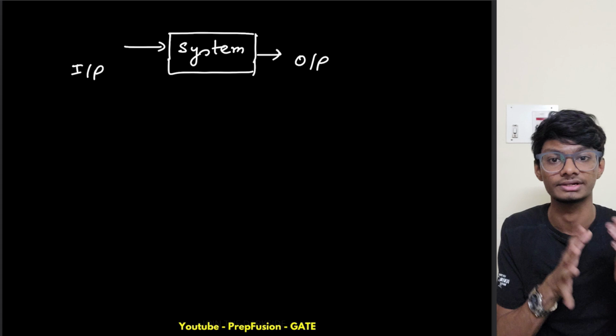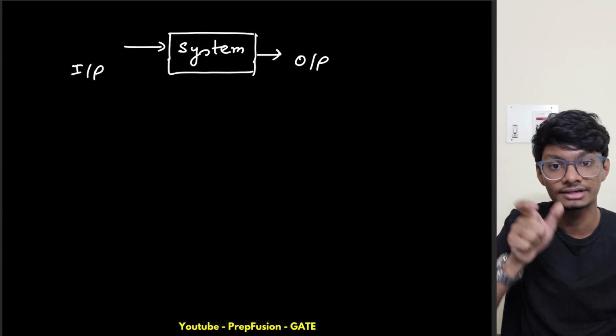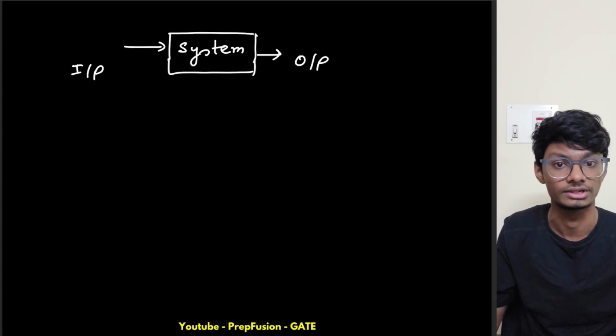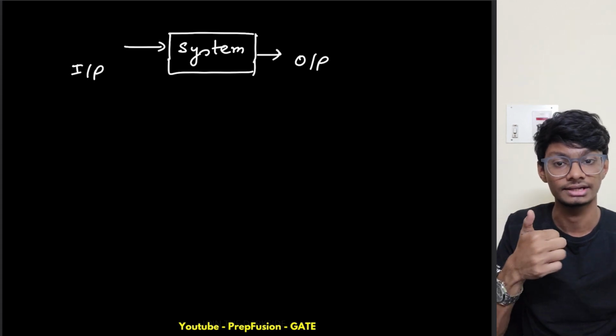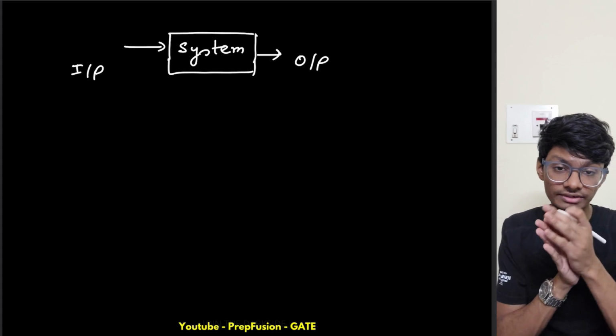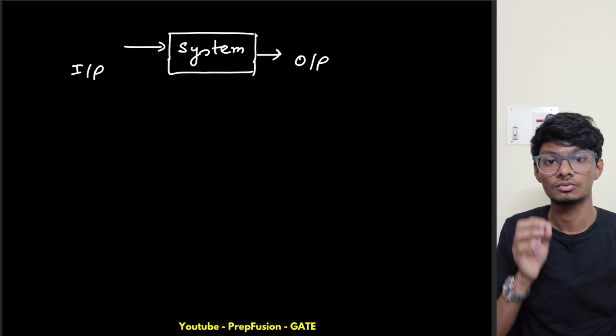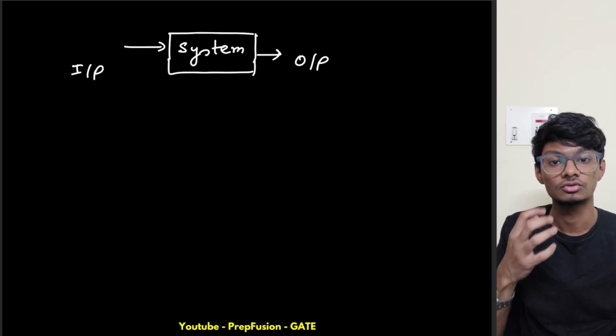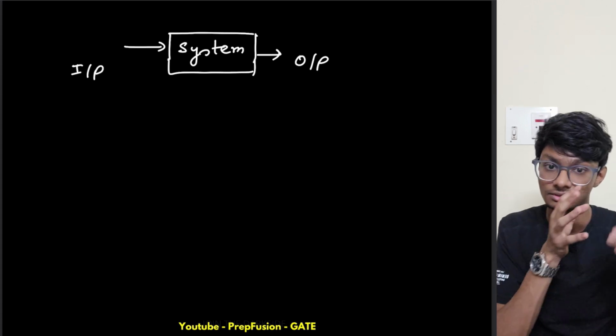It can only dissipate energy, but can it store energy and transfer energy from one place to another? No, it can't. But a capacitor has that, right? A capacitor can change the state of the system. It can store the energy, then transfer it to another system, right? So it has that capability. So what we'll assume as state variable is the capacitor, right?